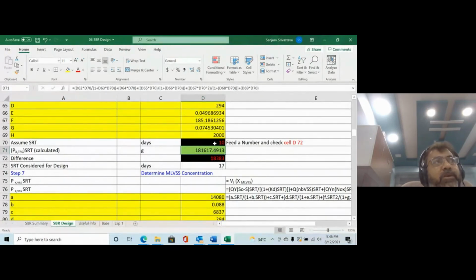Growth means what? Again, understand. Growth means substrate is becoming cell. Death means the cell is already killed. Now the cell has to be hydrolyzed again, right? Because the substrate is still where? Sorry, the particulate is where? It is still in the reactor. So these two equations, where growth and death are taking place together, must be balanced for some SRT.